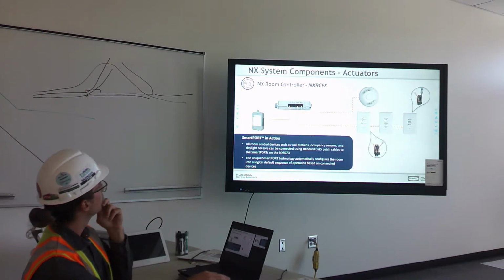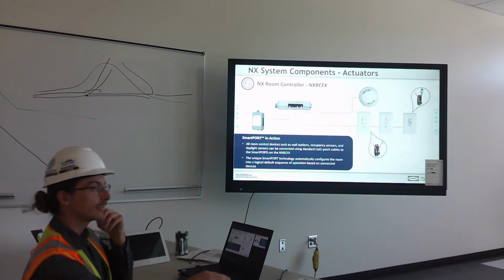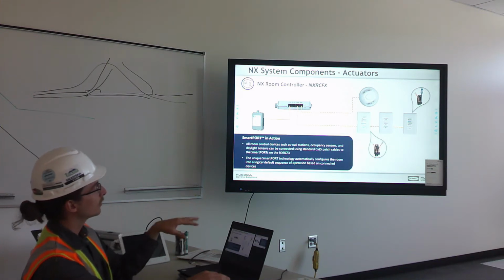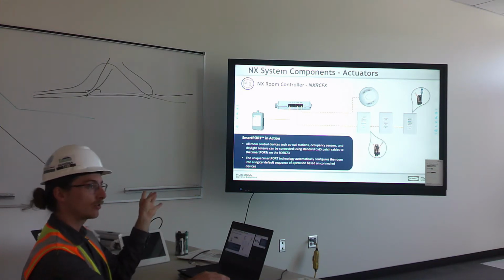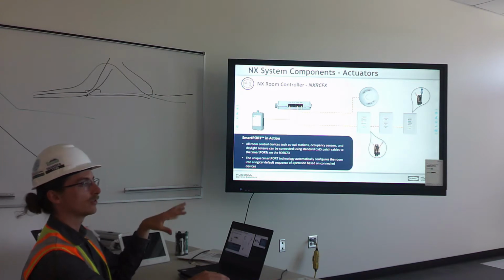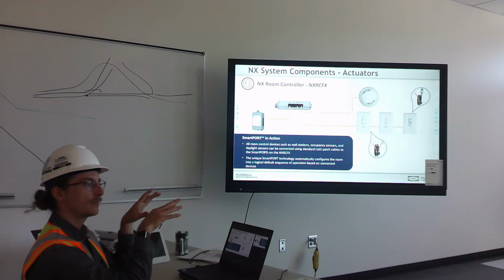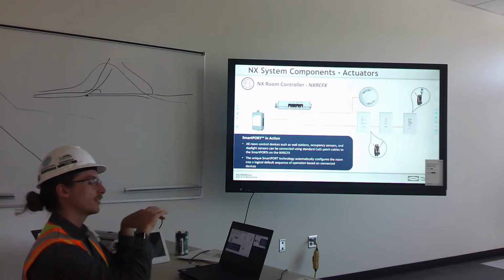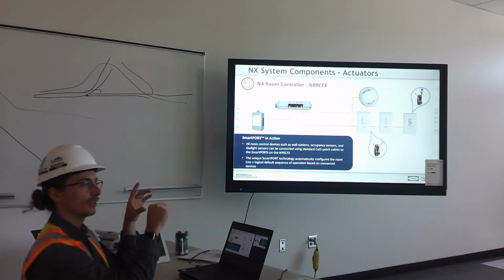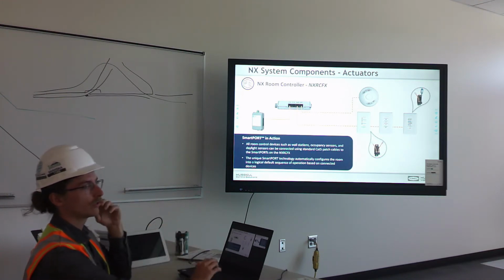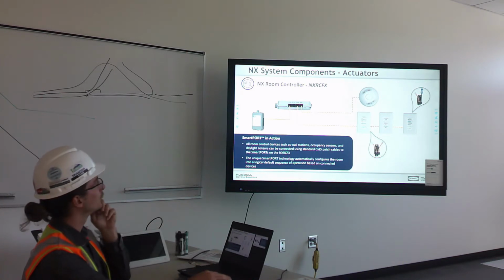So if you have to replace it, you have to reprogram, right? Yeah, they'll have their programming on there. That is one thing where the area controller will come in handy, because there is a feature where if you take out a device and it can't talk to it anymore, and you right-click on it, it will ask you if you want to replace that device with another one. So it will automatically move the programming over to a new controller that you have discovered.